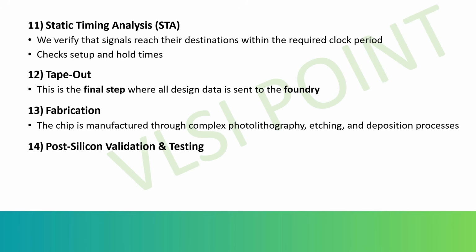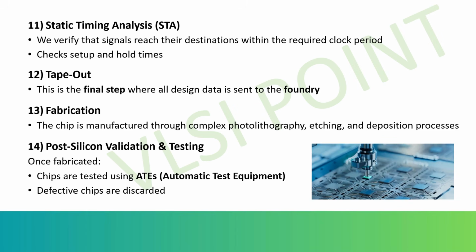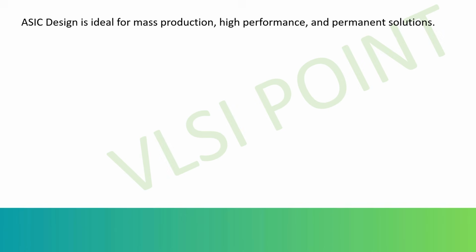Finally, the post-silicon validation and testing. Once the chip returns from the foundry, the task will be to use ATE, that is automatic test equipment, to test each chip. Then measure the performance, timing and power, debug and fix issues using DFT structures, and package the working chips for sale. This ensures your chip works exactly as designed in real hardware. So this is about the ASIC design flow.